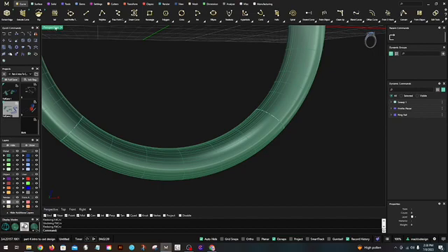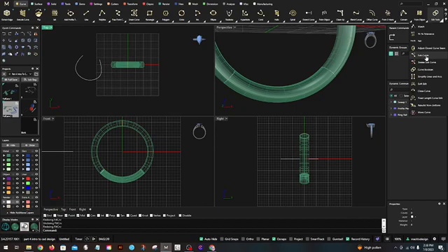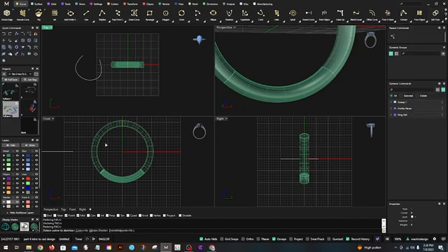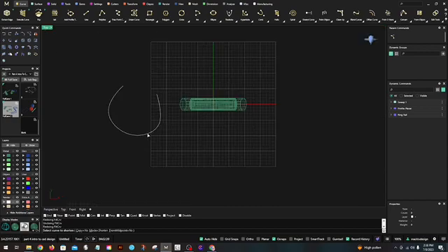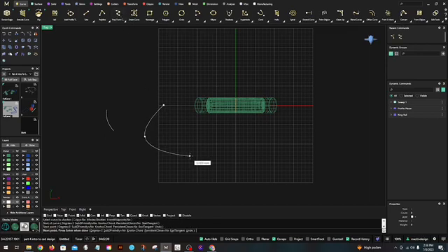Subcurve. All right. I wonder what that is. Let me click on that. Oh, okay. This wants me to select curve to shorten. So if I shorten the curve, I click between where I want it. I'll do it again, and I want this and this. Okay. There we go. Very interesting. I'm going to put another curve out there.